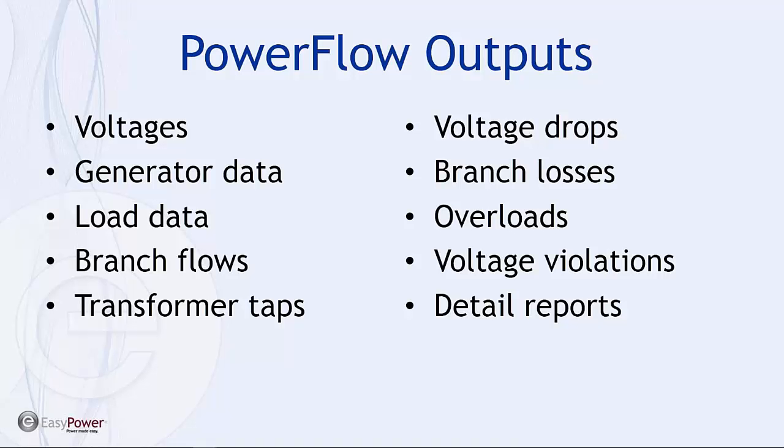And it's that tracking and that trending that will help you identify areas that need preventive maintenance, elements that could be showing signs of wear or having some issue that should be attended to before there's a catastrophic failure, all of which justifies the expense of doing a PowerFlow study or the time invested, because there is a payback more easily identified than you will with just a short circuit analysis.